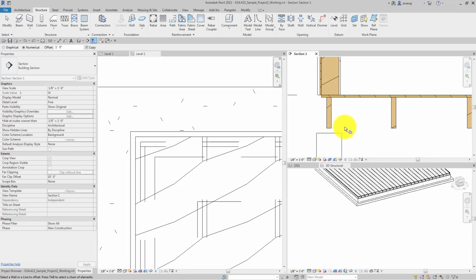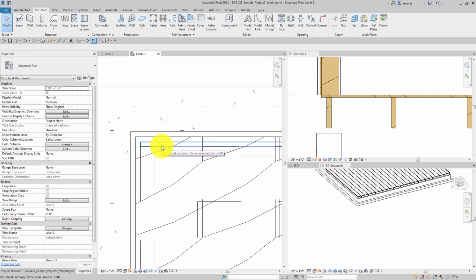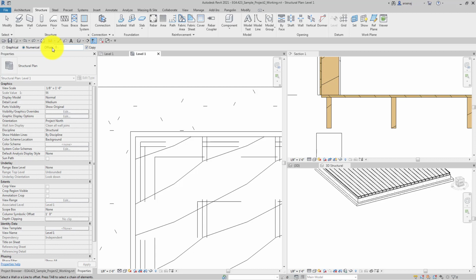So let's offset this beam 1 5/8, this chain of beams. Let's go O for offset, O space, or enter for offset. We can do 1 5/8, and hopefully we can get the chain of beams. This is one thing that's kind of frustrating for me. It doesn't always work. Let's not hit copy as well. We don't want to copy. So there we go. So we uncheck the copy, go to the outer part of the beam, tab, and then